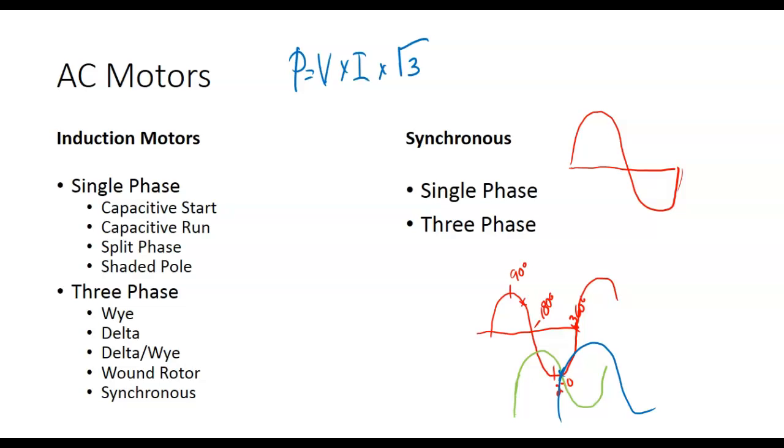Most of your big industries and all your big restaurants run what? Three phase. So that's the big advantage. But it's more expensive to run it just for your house, right? You understand? If we ran that one more wire, instead of having one transformer up on the pole, we'd have to have 3. Transformers cost a lot of money. So high power demands, we use three phase.